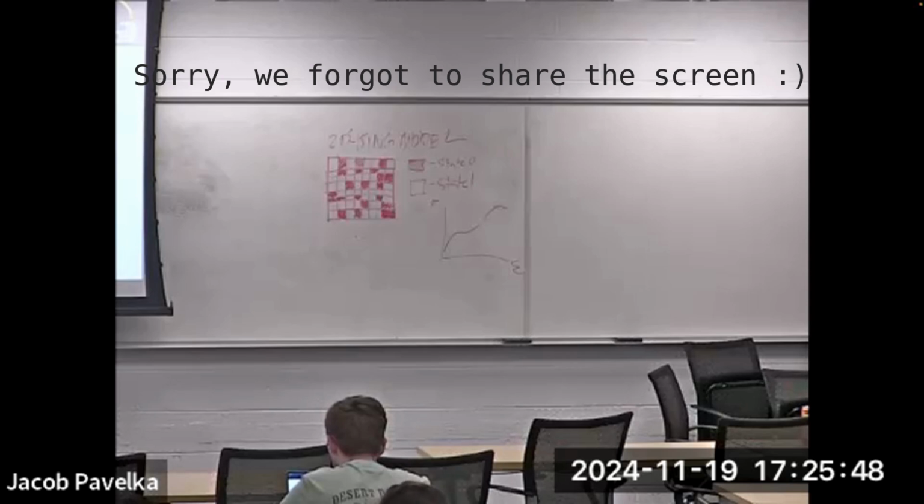We just say this is some macroscopically homogeneous and perhaps anisotropic material. And you define these constitutive laws by doing a bunch of experiments in the lab and typically more phenomenological approaches. But of course, you can try to build in some physical theories as well. Crystal plasticity goes way, way down in length scale. Not quite to the atomic level, but more these grain and microstructure level features.